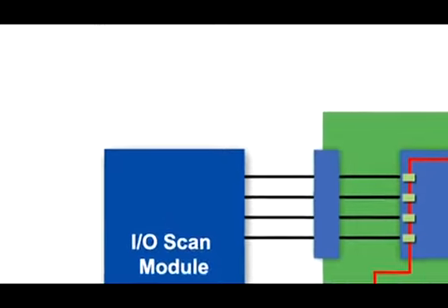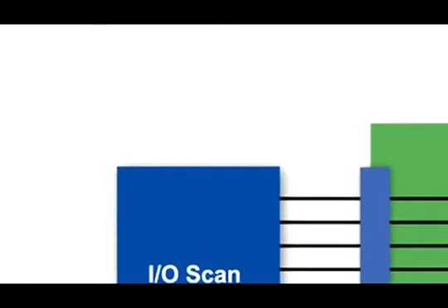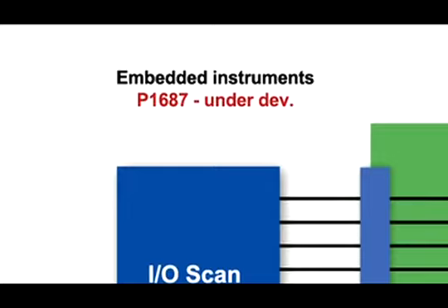To facilitate the use and reuse of these instruments at board and system level in a standardized way, a new standard, IEEE 1687, or IJTAG, is currently under development. This standard for access and control of instrumentation embedded within a semiconductor device will describe the methodology for access to the embedded instruments through the JTAG port, and will provide a standardized description format for how to operate the instruments. Like .4 and .6, this standard is also an extension to the original .1 standard.